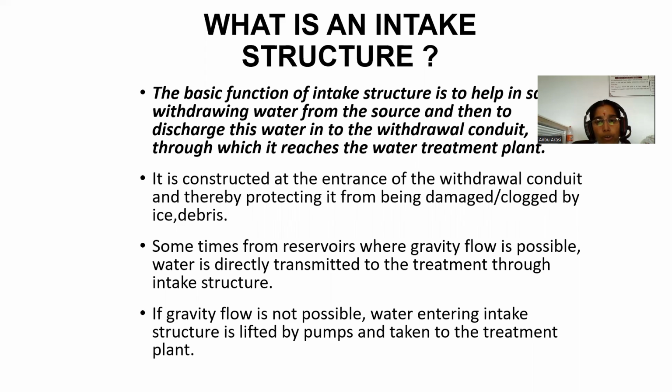Sometimes from reservoirs where gravity flow is possible, water is directly transmitted to the treatment plant through intake structure. If gravity flow is not possible, water entering intake structure is lifted by pumps and taken to the treatment plant.